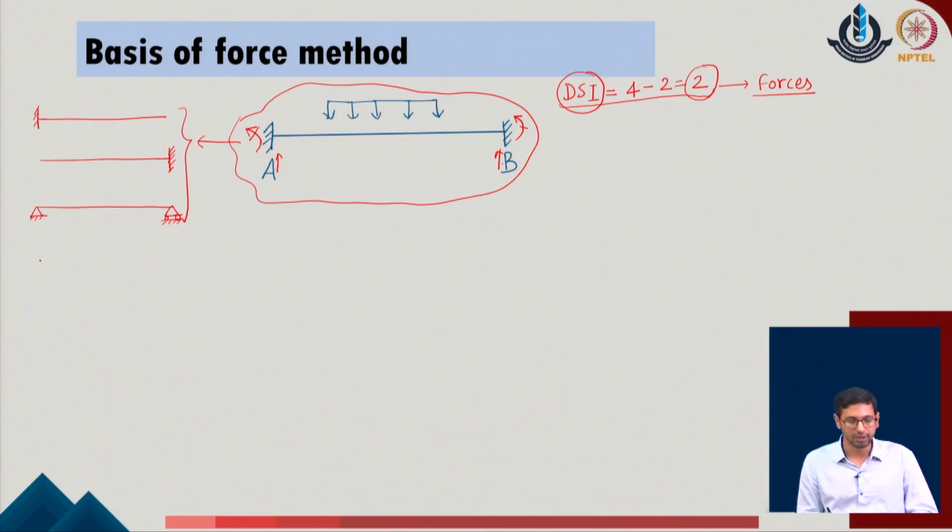One more system could be there which is a little bit more audacious to define, and in that we can say that if I remove the two vertical reactions of the given system, and now consider the remaining ones as the redundants, this will define a system support like this, which is the guided roller with only the possibility of the moment reactions, and that is what will have the two redundants on the given problem, which are now the reactions R1 and R3 for the given problem.